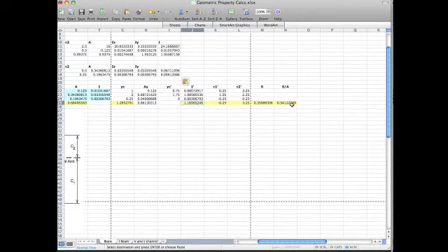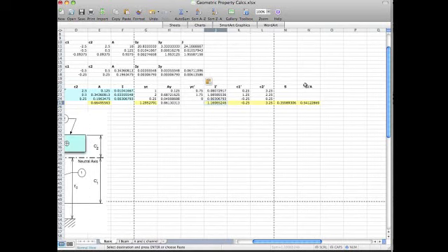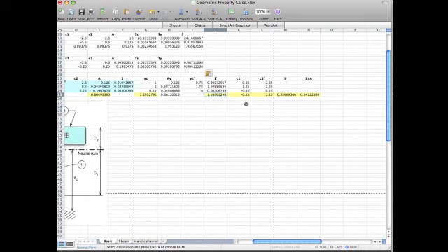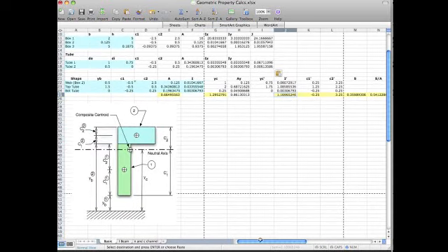The shape factor divided by the cross-sectional area. So this at least gives you a number that you can compare effectiveness strength-to-weight ratios. Because remember, the strength is proportional to S, and the weight is going to be proportional to cross-sectional area. So looking at S over A gives you basically a number that speaks to the effectiveness of the cross-section to carry load versus its weight.